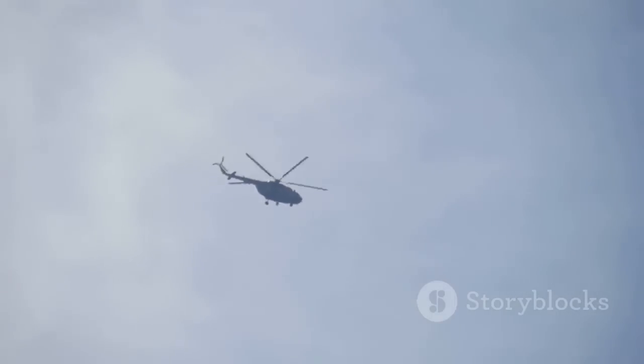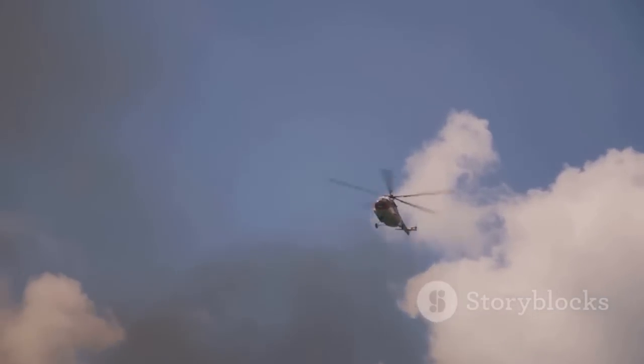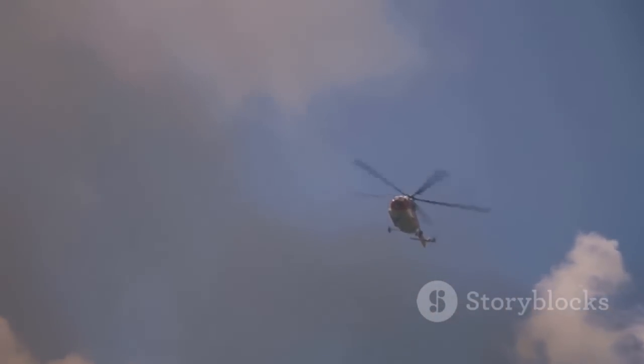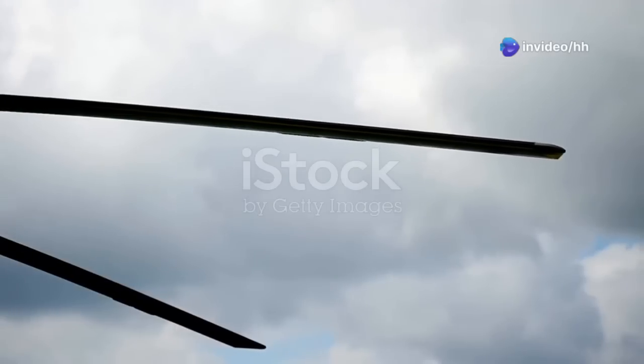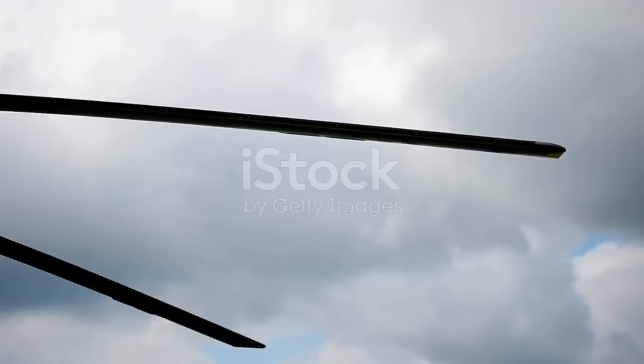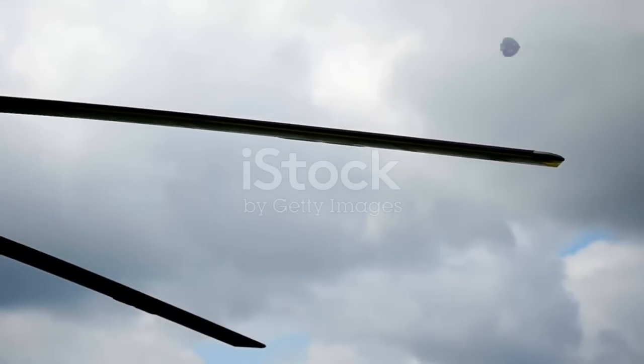But why is this twist so important for helicopter performance? It all comes down to maintaining even lift distribution across the entire rotor disc, the circular area swept by the rotating blades. This is crucial for stable and efficient flight. As the blades spin, the tips move much faster than the sections closer to the hub. This difference in speed can create significant aerodynamic challenges. Without blade twist, the faster-moving tips would generate significantly more lift than the slower-moving inner sections, leading to instability and control issues. This imbalance could make the helicopter difficult to control and less efficient.